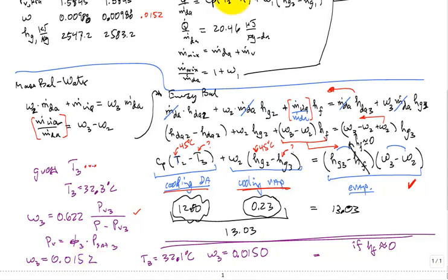So this one is also common to neglect. But if you don't neglect it, and in this problem it was coming in at 25 degrees C, I don't know if I gave that value of h_f at 25 degrees C. Let me see if I have that. It's 104.9 kilojoules per kilogram.